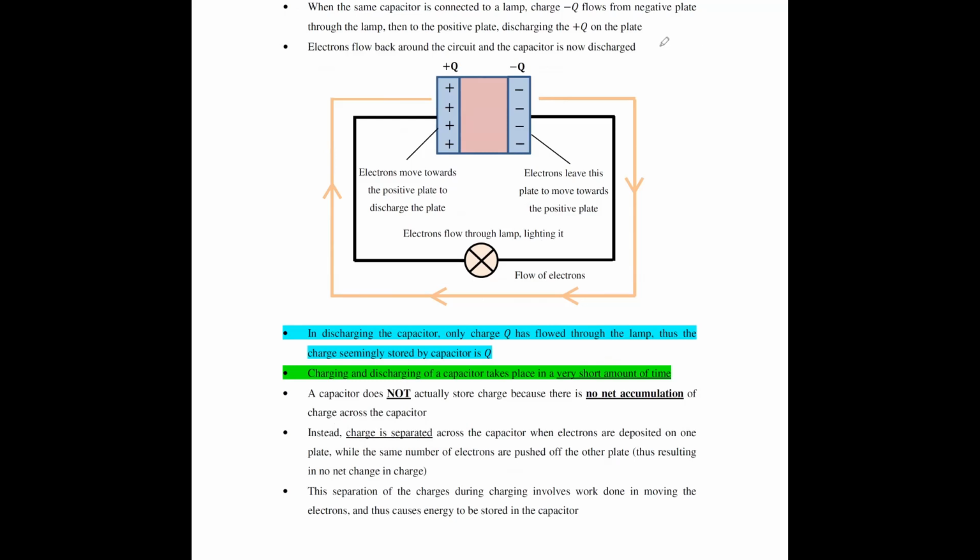But if the exam question specifically asks you whether a capacitor stores charge, you actually should not say that, because a capacitor doesn't actually store charge. The reason is that there's no net accumulation of charge across your capacitor. When it was originally fully charged, you have a charge of negative Q on the right plate and positive Q on the other plate.